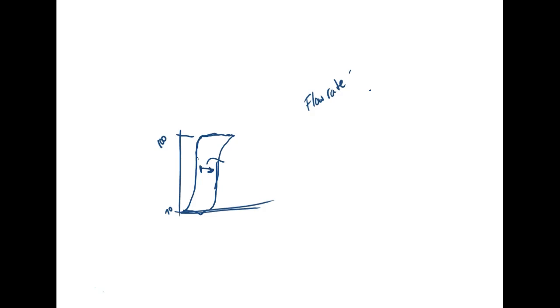But the problem is, if you run off your compressor, then normally, if it's a piston compressor, you're going to get oscillation. In some situations that's not bad, but if you've ever done spray painting, that's critical. You wonder why these paint shops have these extremely big compressors, or they use what they call continuous flow compressors, which means they usually use a turbine that spins all the time and generates exactly the same flow rate and exactly the same pressure. You guarantee service quality.